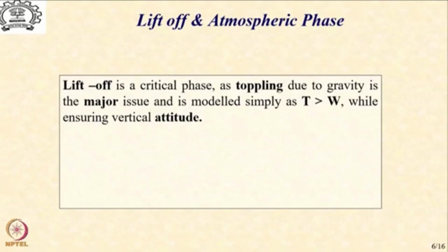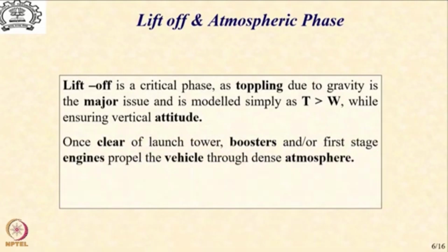From a mechanics point of view, it is generally modeled as the thrust, which is the forward force, being greater than the weight, so that it will lift off and start moving vertically. You must ensure the vertical attitude during this phase. Once clear of the launch tower, boosters and first stage engines propel the vehicle through the dense atmosphere.